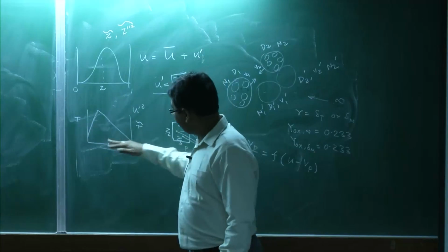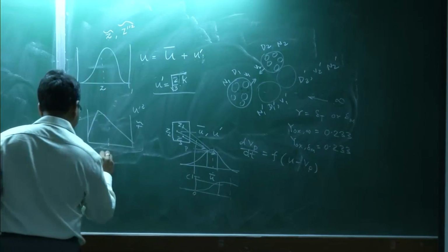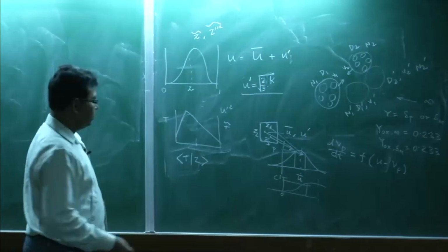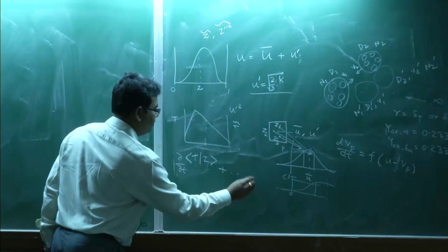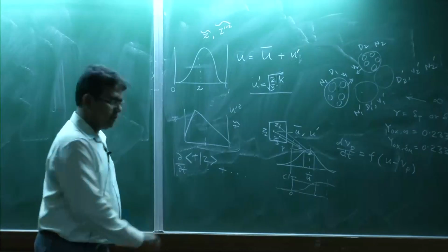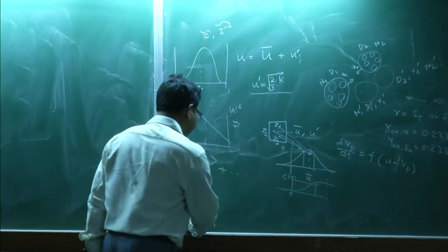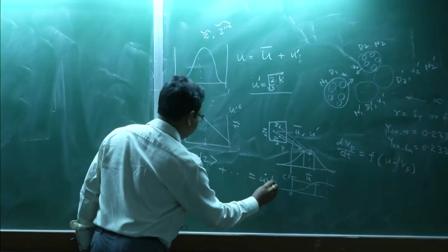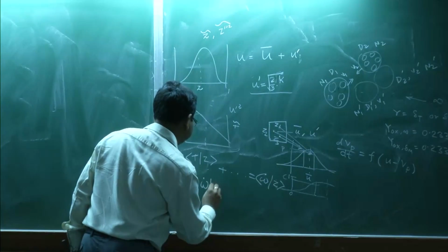Here we are directly solving the temperature as a function of Z. This is the mean temperature as a function of Z, and we are solving a transport equation for that. Then there will be the reaction rate source term on the right hand side, and this is also a function of Z.